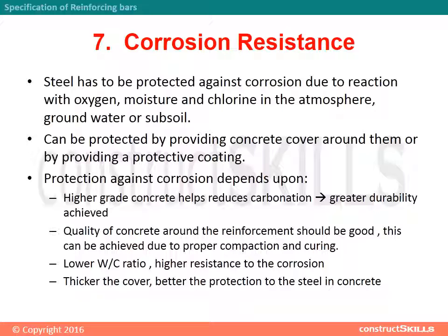Protection against corrosion depends on several factors. Higher grade concrete helps reduce carbonation, and greater durability is achieved. Quality of concrete around the reinforcement should be good. This can be achieved by proper compaction and curing. Lower water-cement ratio gives higher resistance to corrosion. The thicker the cover, the better the protection to the steel in concrete.